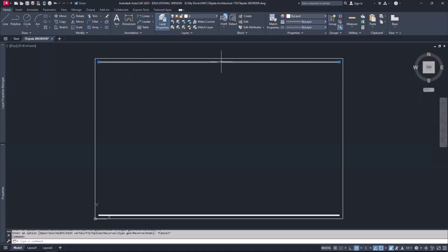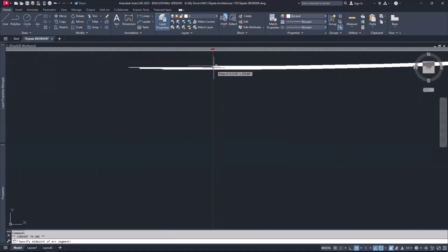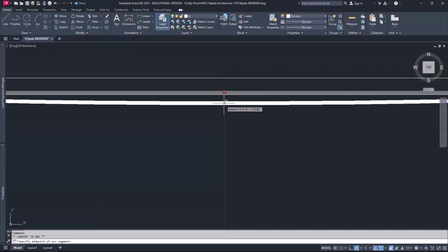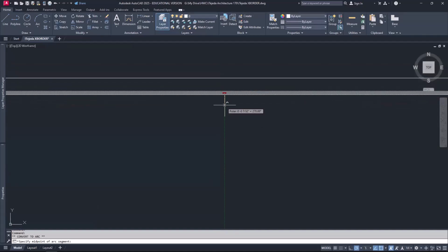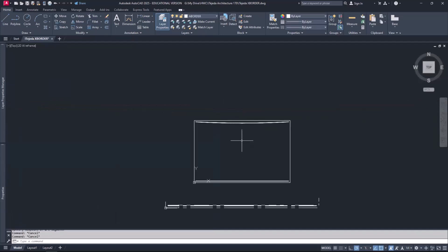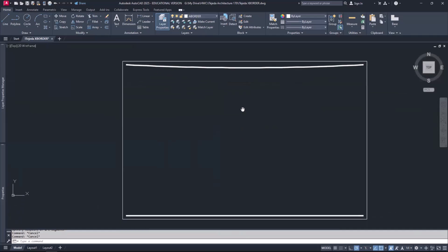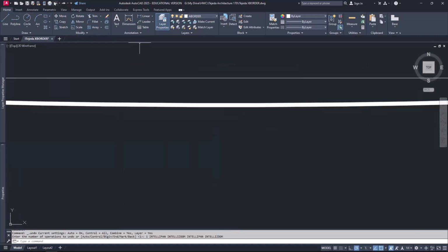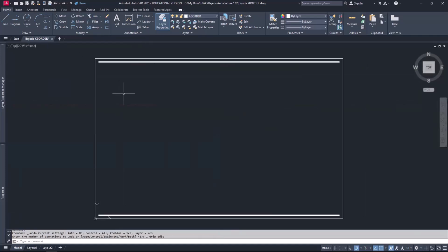It's a polyline, and if I hover over this midpoint grip, I can convert to arc, and then I'll just bring it straight down just a little bit, and I've got to zoom in here for a moment. And I don't want to really be exact, so I'm just going to pick right here and click, and then tap my escape key, zoom out, and now I have a nice curve to it, a gentle curve, if I wanted that. So I'll undo, and I'm just throwing options out.